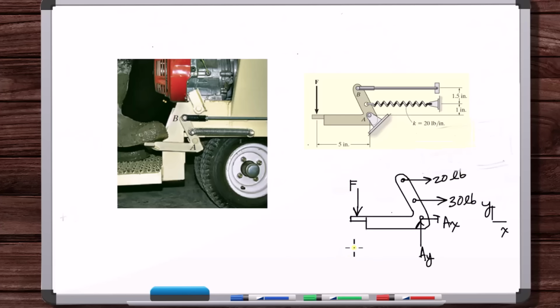So let's take a look here. How does this fulfill the requirements? Well, first of all, the bracket has a plane of symmetry that passes through its center axis, right? If you think about into and out of the page, the thickness of this link, it has a plane of symmetry down the center line. It's symmetric. Okay, and so thinking about the forces, if we were considering the weight, you can put the weight of gravity acting at the center of mass. And gravity here would be acting, if we were considering the weight of the link as non-negligible, straight up and down in that center plane.